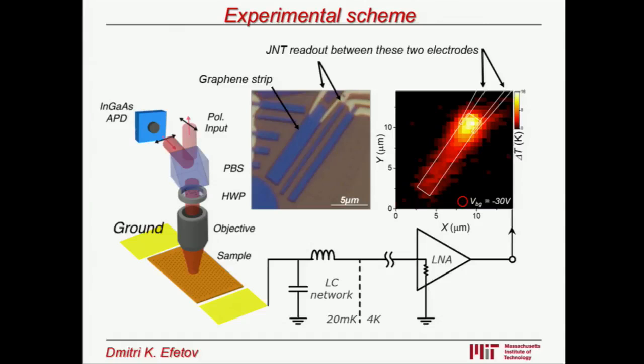We can treat that system as a series of resistors, and it scales. If there were a contribution from faraway electrons to the Johnson noise, it would decay as 1 over the width of that device. We expect the width here is like 2 microns, I think. So 2 microns away, this effect is gone. So whatever signal we get from a faraway point here is really just the thermal conductivity of the electrons. It's not an artifact.